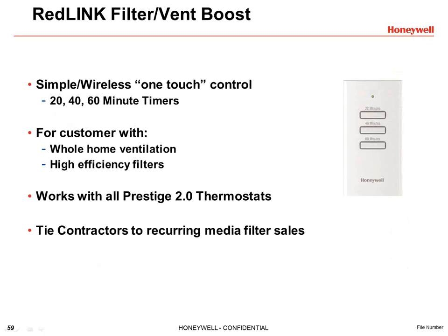They've also got a filter/vent boost. So this, we've used it mainly with ERVs, HRVs, where you can put this in a bathroom and just touch a button and it's going to run for 20 minutes or an hour, whatever button you push, and it's going to automatically boost it. Some people use it for the fan, to get 60 minutes of air cleaning or that kind of thing. So different options with that filter/vent boost control. And again, it's wireless, so you can put this thing wherever you need to.